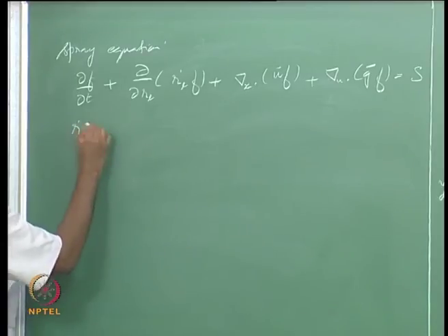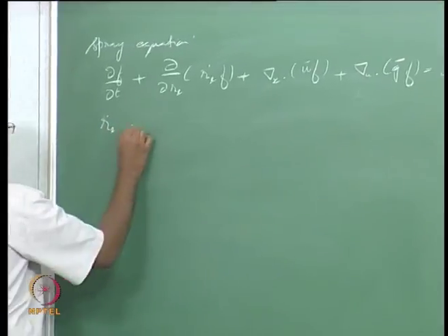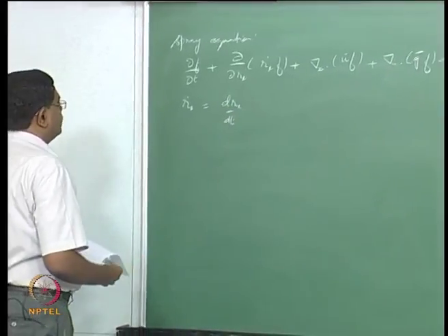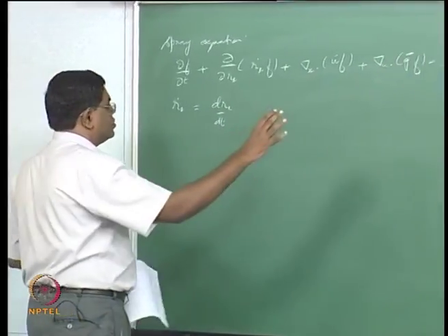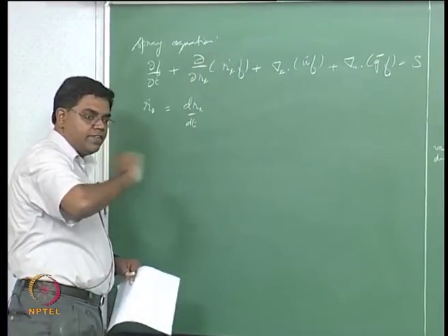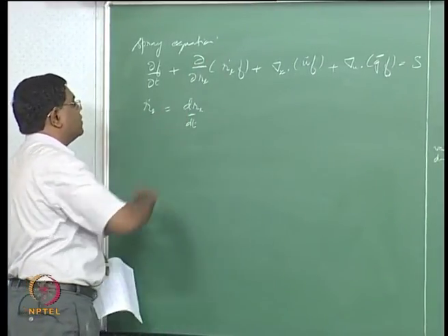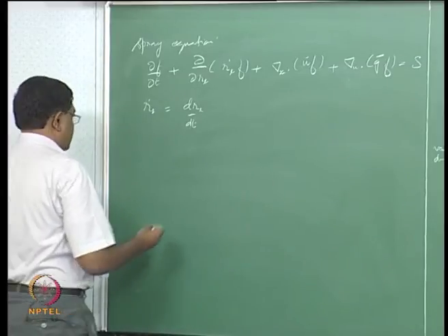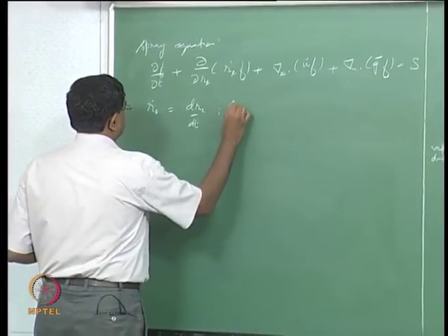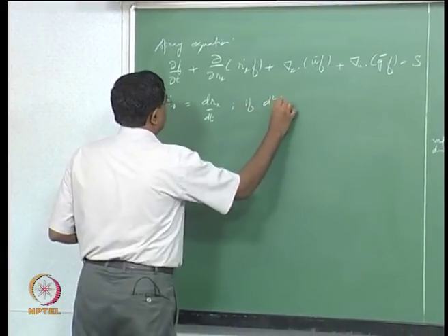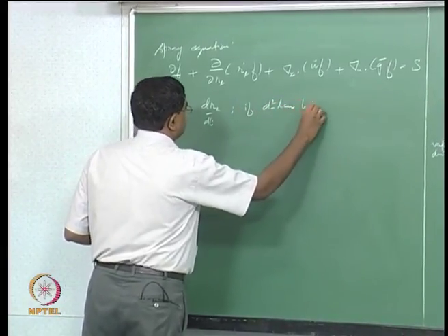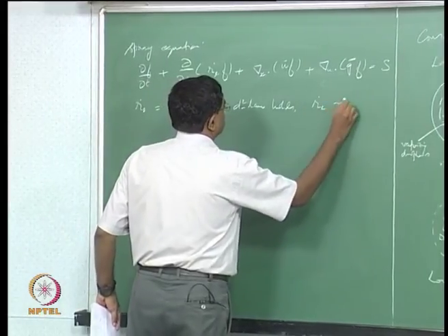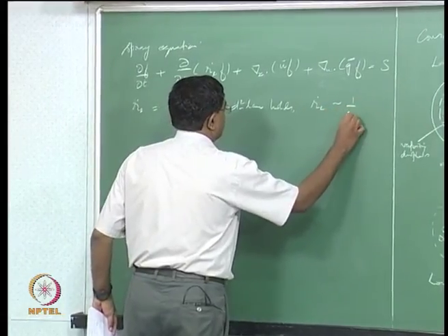r_L dot is something that we are familiar with, which is dr_L over dt. So this basically tells how f is going to change because you have evaporation or burning that changes the r at a certain rate with respect to time. And for example, if the d squared law holds, we know that r_L dot goes as 1 over r_L.